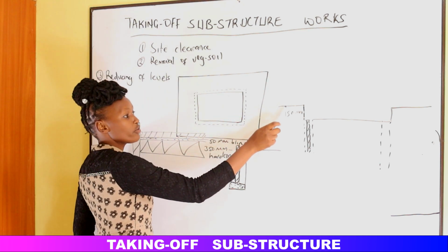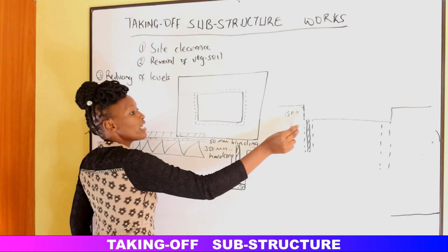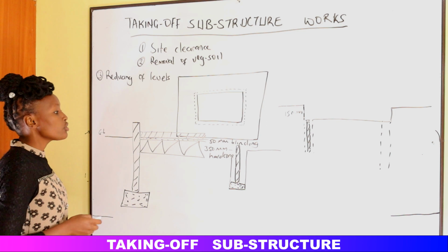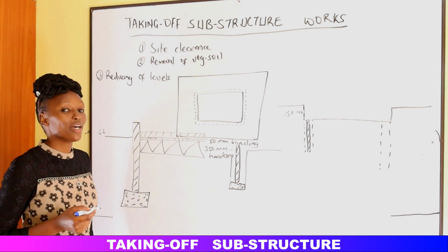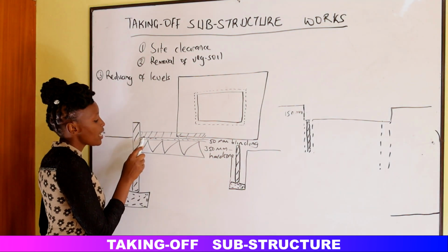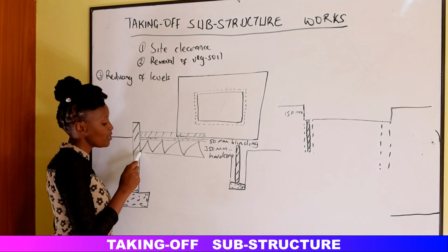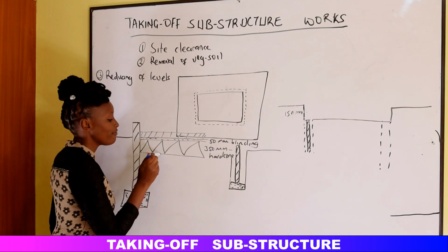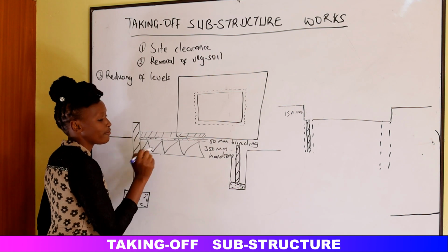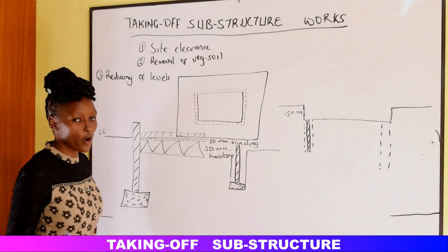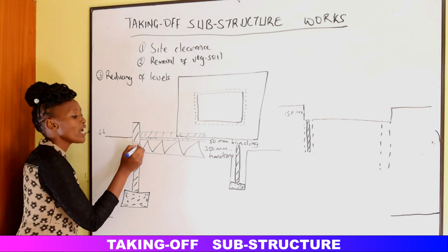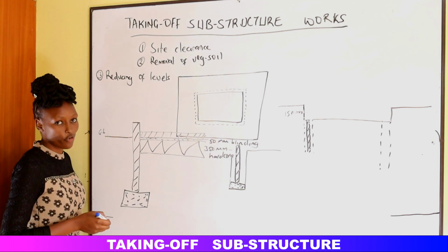We excavated the vegetable soil, removing 150 millimeters thick. To know whether we shall reduce the level, we calculate from here up to below the hardcore. This level is where construction can be done. We will take 50 plus 350, we will get a total of 400. So from the ground level, we need to go down to a depth of 400.